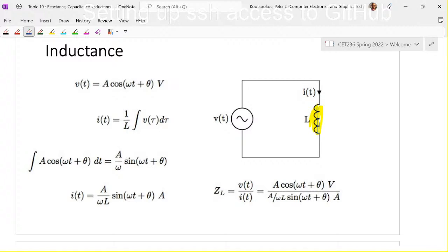And the choke is a sort of inductor. It's usually particularly designed. Chokes are usually tuned to whatever the mains frequency is. So 60 hertz here, and it's to get rid of any mains hum on the data communications on the USB cable. Mostly you don't need them. Usually just some shielding's enough. But sometimes you need a choke, particularly in a lab environment where there's lots of stuff happening.